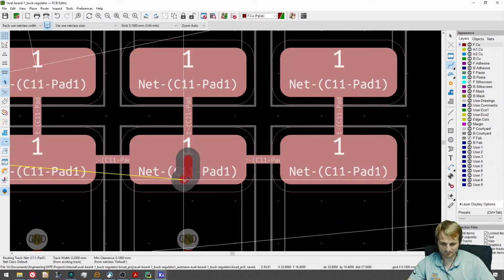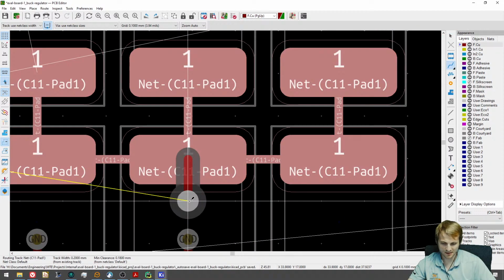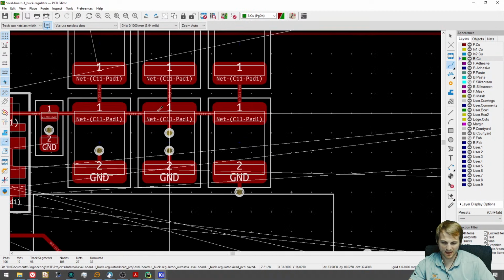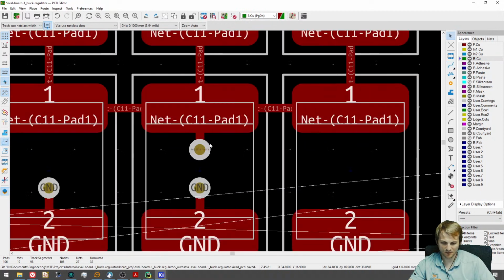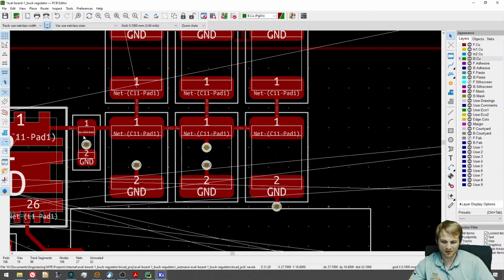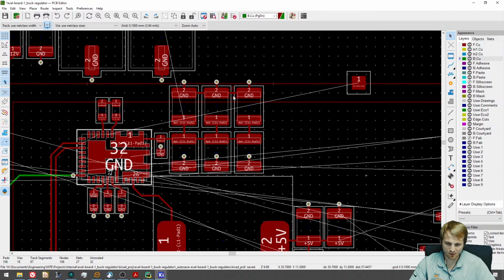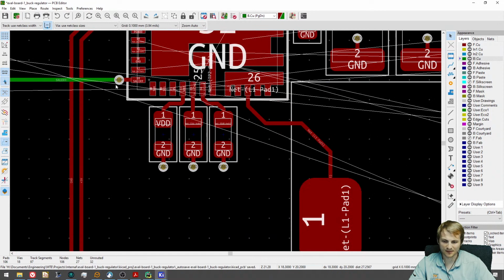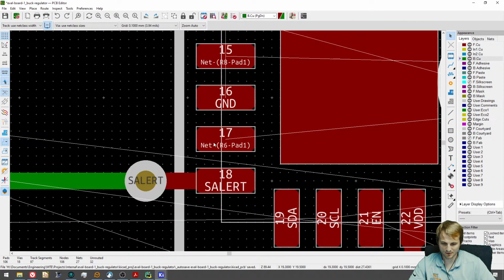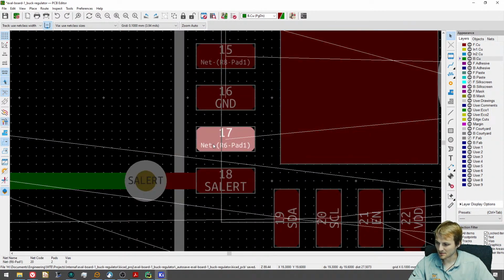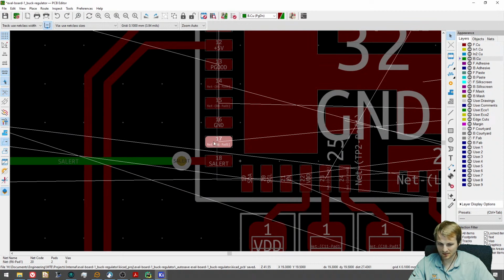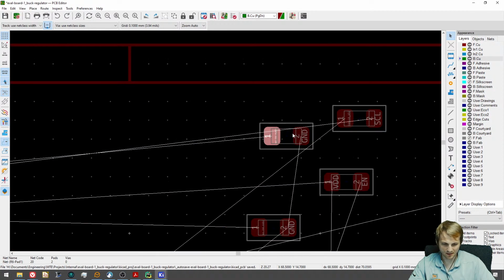And another potentially better example is, let's say we had our power coming in on an inner pour. Now the loop area is even closer on this side. So the closer you can get your input vias to each other is always going to be better. On like 1210 caps, it's not as big of a deal because the loop area is already pretty massive, but you still do the best you can. So that's the RT sync pin.